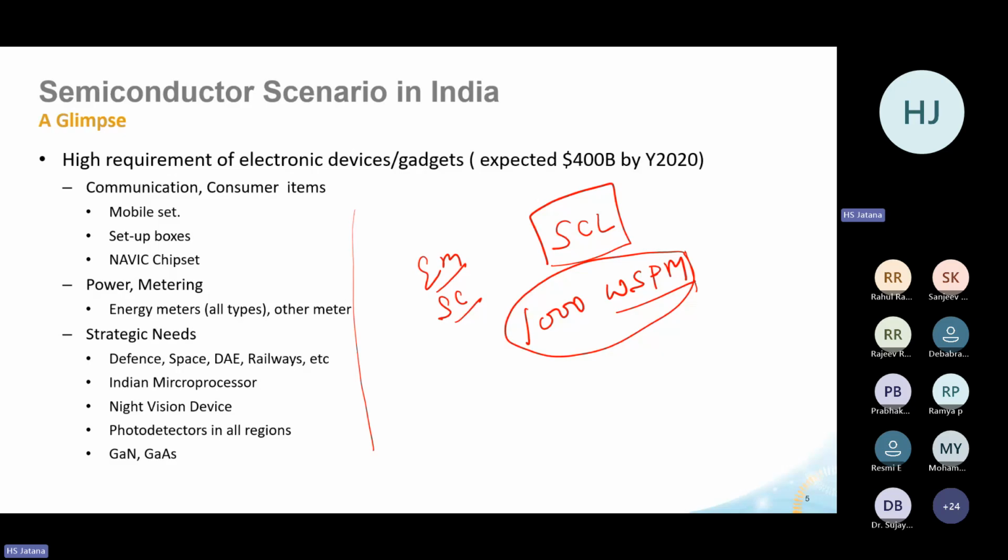We have some fab equipments which are installed at Sensei, IISc, IIT Bombay, and at many other places. But you cannot make a good transistor out of those things. Some limited experimental academia things can be done there. You can grow some layers, do some etching. But for making a good transistor, you need a very good profile. For that, you need ion implanters. And it's not one ion implanter. There are 4 different types of implanters, and you need all those 4 different types of implanters for making even a good transistor. Which can only be made by commercial equipments and not in any academia.